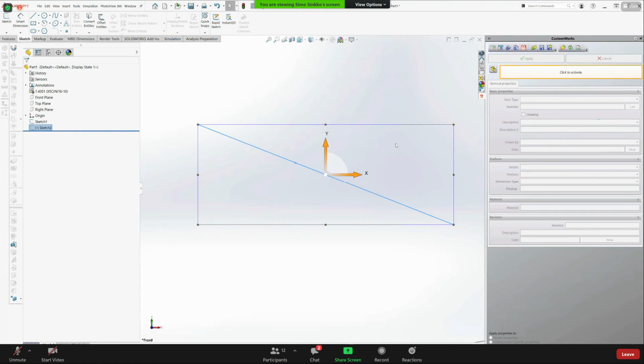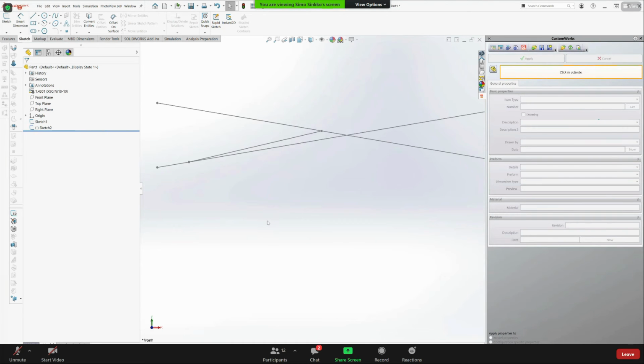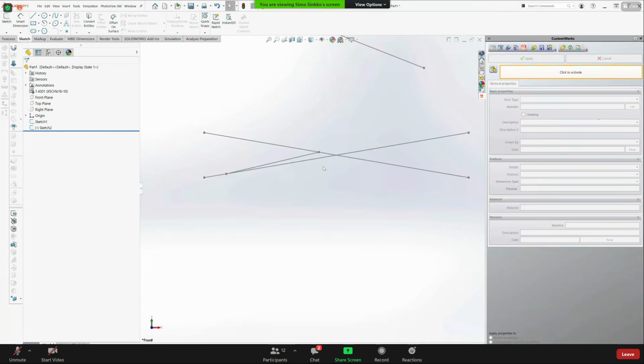immediately, but you need to play a little bit and find out what could be, depending on how big cylinder forces you get, you are able to calculate what should be the correct diameter for the cylinder. And then at the same time, you need to find out such a cylinder that the assembly length, so the minimum length, is suitable, and it can create a needed stroke in your system.